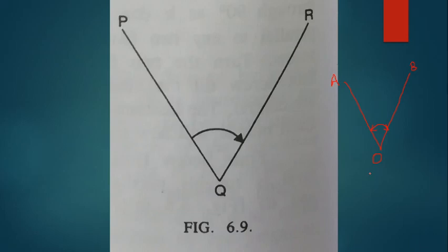But when you release the upper clamp alone, that means the lower clamp is tightened and the upper clamp is loosened, then there will be only movement of the pointer or vernier A0 mark, the movement of verniers only on the main scale. So there will be a relative change. These 2 points are to be remembered and do not confuse them. When you release the lower clamp alone, the reading will not change, and when you release the upper clamp alone, there will be a change in the reading.